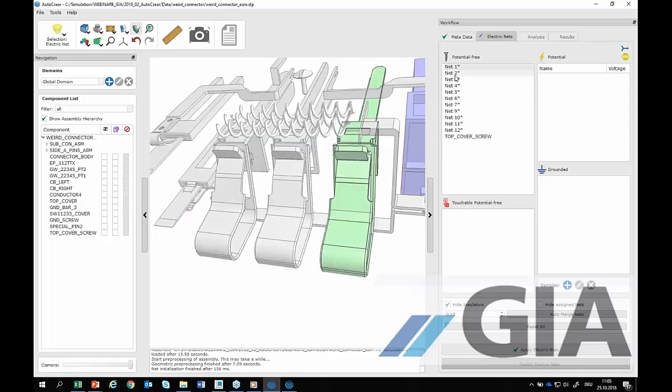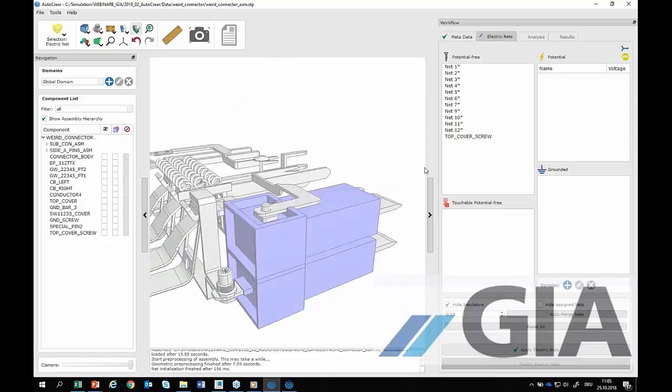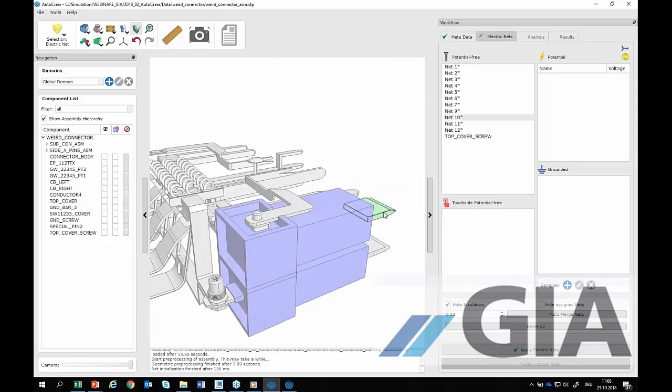Here I'm also getting the capability to bring some nets together. Here I have a surface net, and here I have a physical component net, and inside that blue part there is a connection between them. Therefore, right mouse button, I have to merge those nets. And we'll see the number of nets here will be decreased. I'm doing the same down there between that guy and that guy. I want to do a merge.